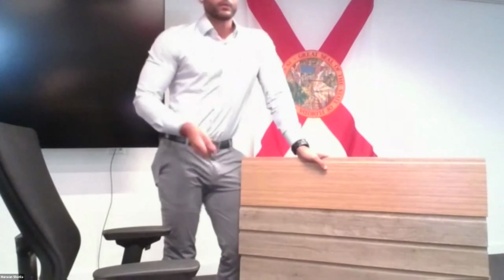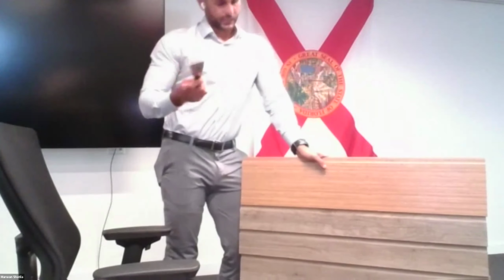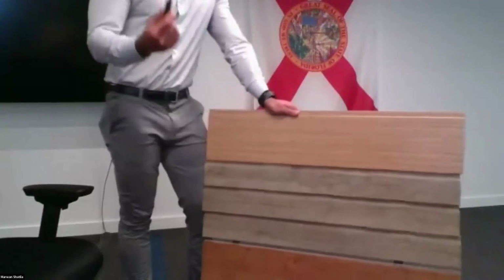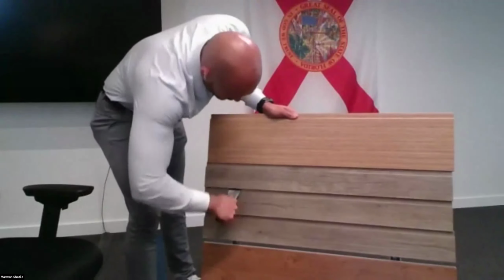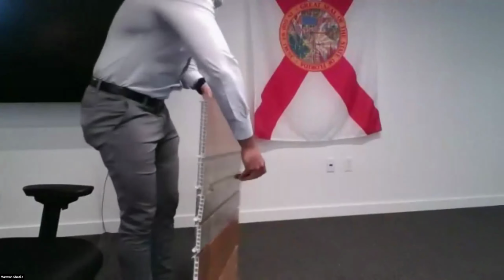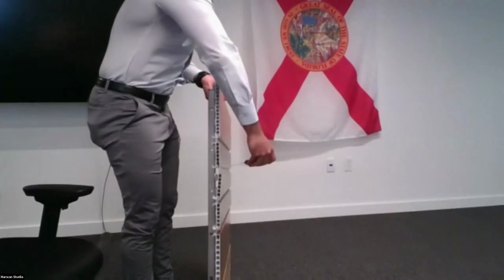Let's say a ceiling application or a ceiling is installed on a building and direct access is necessary for the plenum. We have details to illustrate what an access panel would look like, but if you did need to access the plenum for whatever reason, change in electrical or what have you, you wouldn't need any kind of fancy gadgets. The maintenance team could do this themselves. All you would need is a putty knife and a few hands, where you tuck the putty knife into the panel. You show that on the side right here, hopefully all you can see.